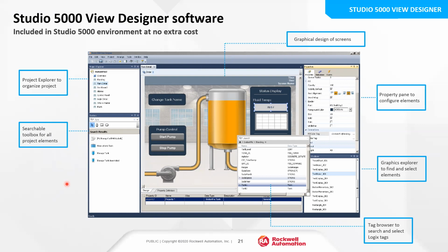One important thing to note is that, like we said earlier, you can take a PanelView Plus 6 application and move it to a 7 with no problem whatsoever. You just basically convert your 6 to a 7 inside of Machine Edition. There is no ability, at least at this point in time, to take those PanelView Plus 6 or 7 applications and convert them into a PanelView 5000. So there is no migration tool that'll bring a Machine Edition application into a Studio 5000 View Designer application.